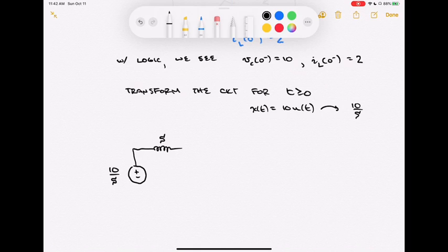Because there was an initial condition, I know I can put that initial condition generator, and it goes something like a minus plus. That was something we just derived, and that minus plus in this particular case is going to reflect the initial current through the inductor. And that was just IL of 0. So this is going to be 2 in there, something along those lines.